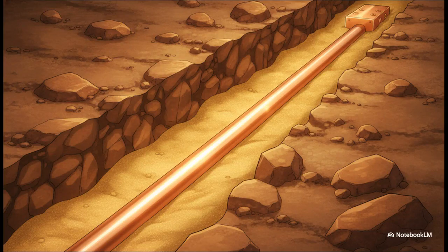And the physical installation itself is strictly regulated to protect this infrastructure. Your grounding conductors must sit in trenches that are at least 500 millimeters deep. And you don't just dump the excavated dirt back on top of them. The cables are actually sandwiched in clean sand, 100 millimeters below and 200 millimeters above. This is crucial because it protects the soft copper from sharp rocks and ensures really uniform soil contact. Finally, all of these trenches and cables route all the way back to the main earthing bar, tying the entire plant into one beautifully synchronized equipotential zone.